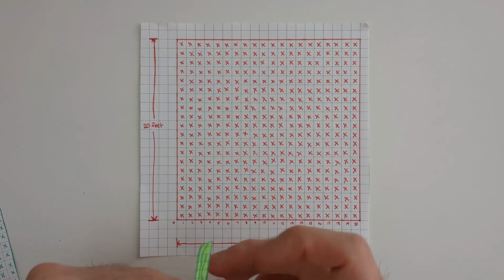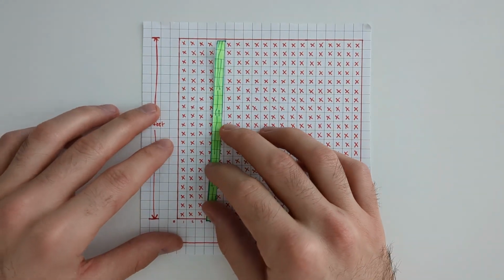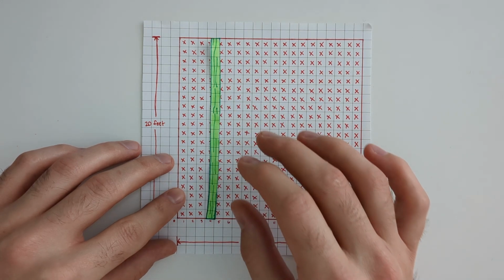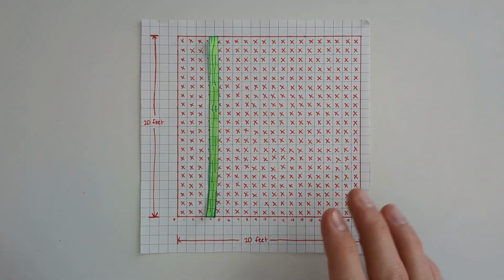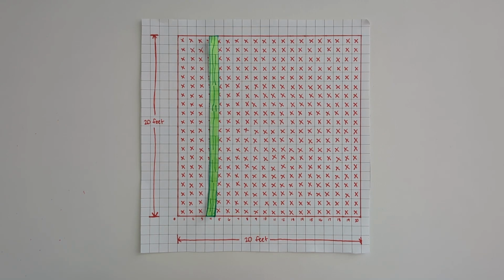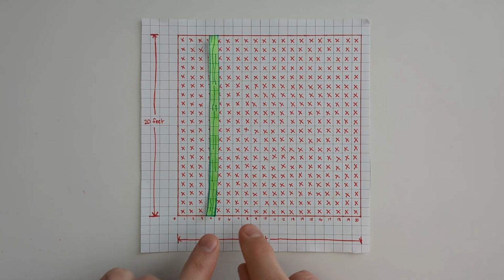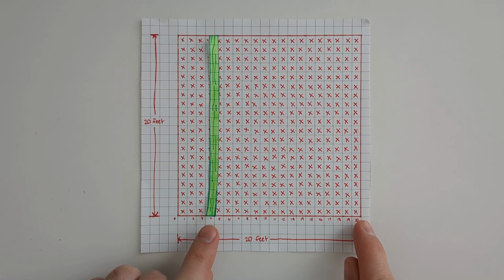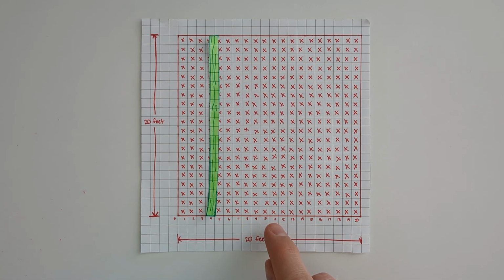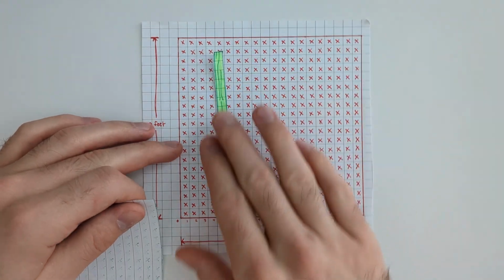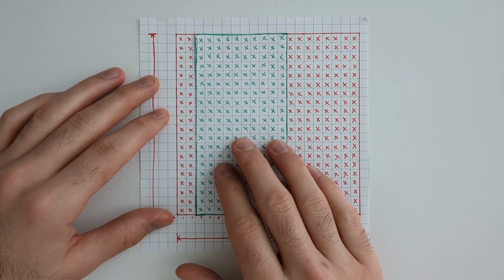If we shift our beam to, let's say, 4 feet from this left wall, then the concept still applies. We reach out to the wall on its left and say, "Hey, I'll meet you halfway." That distance is 4 feet, halfway is 2 feet. The distance here to the next wall is 16 feet, halfway would be 8 feet. So 2 feet here, 8 feet there, that's still 10 feet. So our tributary area won't change.